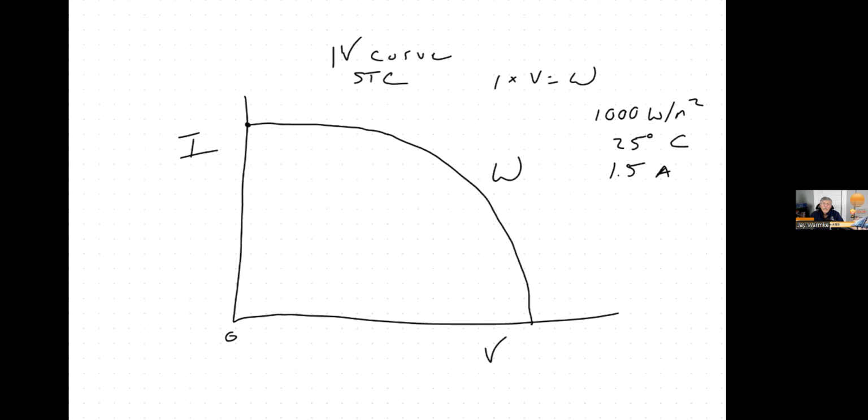So basically, we're worried about how much sunlight. What standard test conditions represents is basically a clear sunny day at sea level when the temperature is about 77 degrees Fahrenheit. This is what we're measuring. We just needed to compare apples to apples, so we picked this as our reference point. It could have been anything, but as long as everybody agrees, now this 400-watt panel is going to be the same as that 400-watt panel. Why? Because we measured them under the same conditions. So it's just a gentleman's agreement.